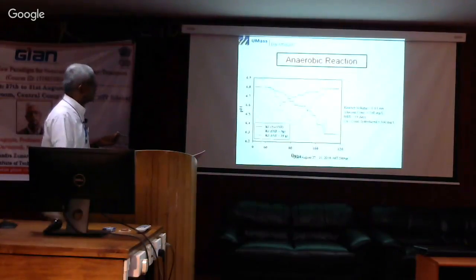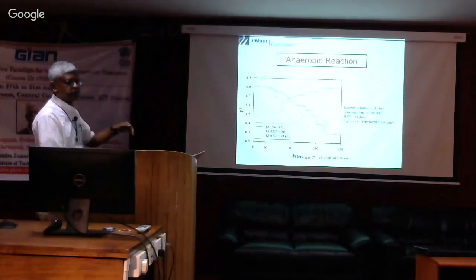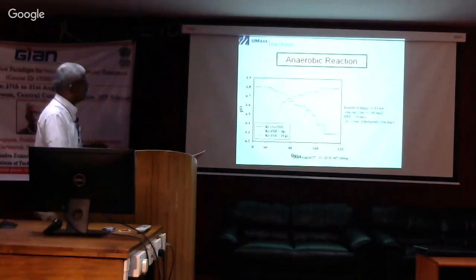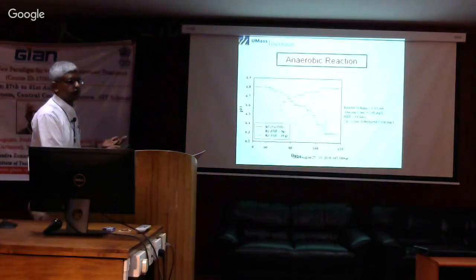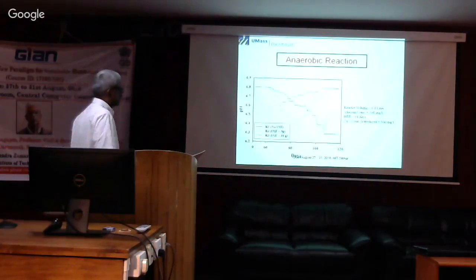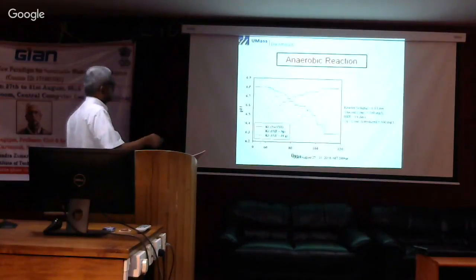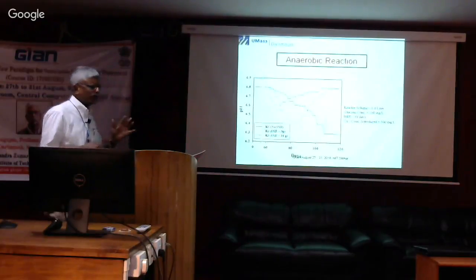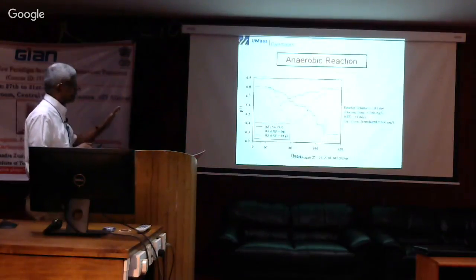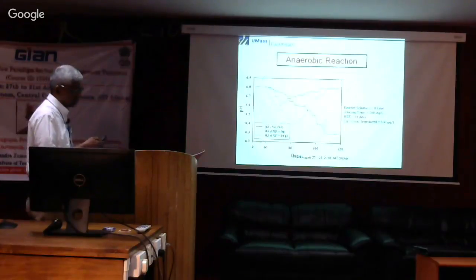Now the question is, how steep is this drop? And if this drop goes to, let's say, a pH of 4, then of course, no way the reactor can survive. So at its worst, what is the pH? Here you see the pH was 6.8. At its worst, the pH was 6.4. So not a very major, this is not an upset causing situation.